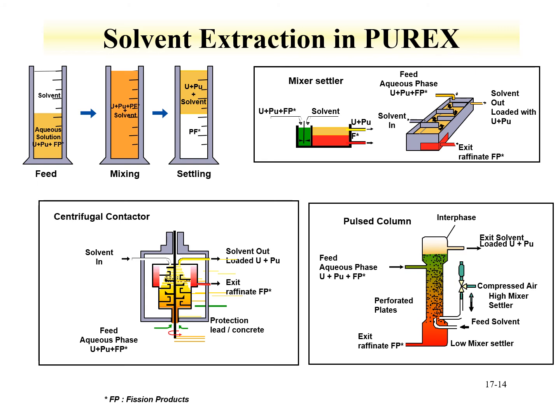Another route, and we'll discuss this in a little bit more detail, would be a pulsed column, where we could put an aqueous feed at the top of the column. The aqueous is heavier, so it would drop down the column, mixing with the organic phase on the way down. The chemistry would occur, so this uranium and plutonium would be pulled out of the aqueous phase into the organic phase. And then at the very top, we would have an organic layer, which would then be loaded with the solvent, and then we could carry that out to another pulse column to do more chemistry.